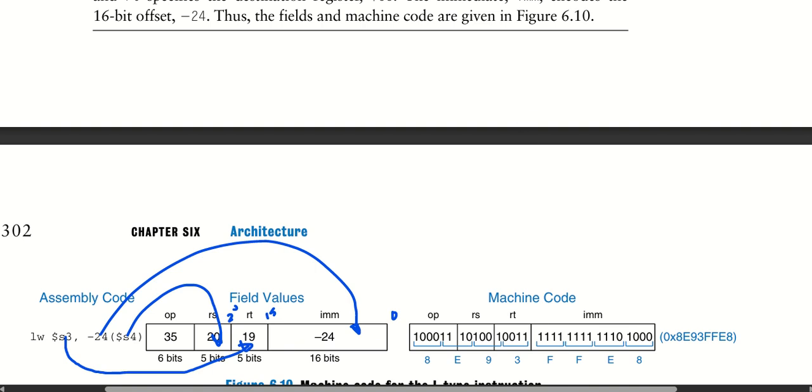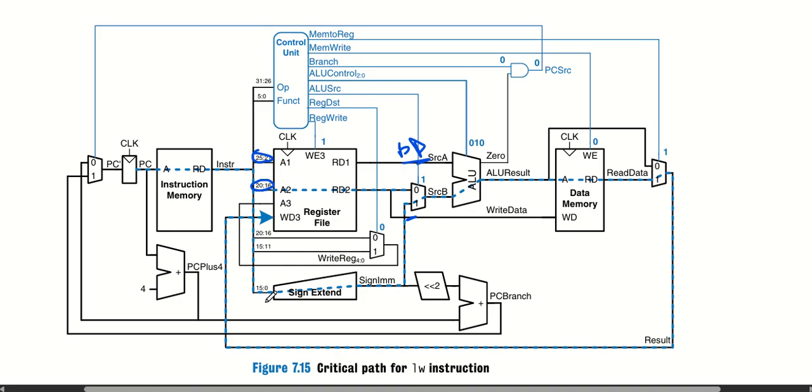That's sign extension. So this one will take maybe 16 bits, so that's why here is small and here is long, right? To pad it up to 32 bits. If the first bit is 0, it will add 16 zeros to make it 32 bits. If the first bit is 1, it will add 16 ones to make it 32 bits, right? So that's the sign extension.